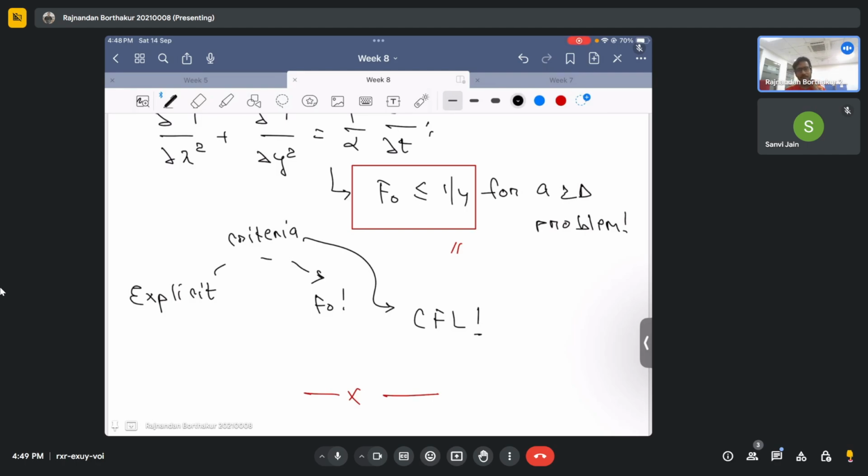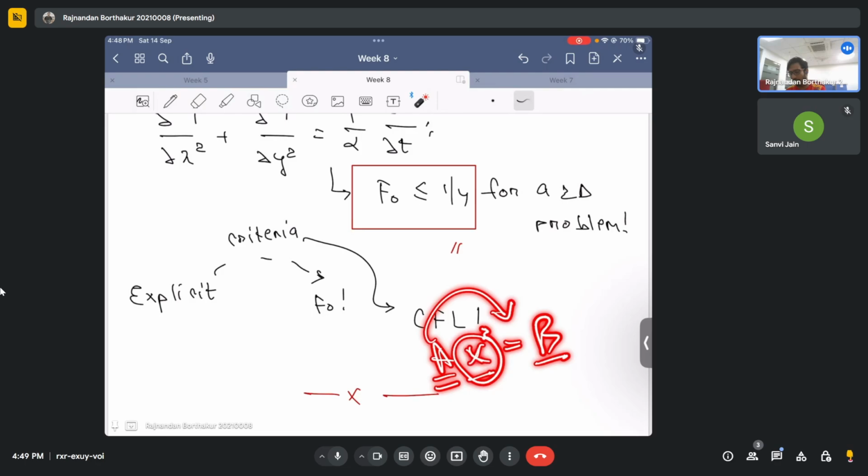Did you understand at least some bit of how these things go on when we try to solve it numerically? Yes, we have not done one thing. So far we have just learned to discretize the equation, but our job is not done there. After you discretize the equation, writing the algebraic equations, you need to form the set of algebraic equations into matrix form, some A matrix times X equal to some B matrix. Basically you need to solve for this X matrix. This X matrix will store the temperature values at each and every node point. And you just need to take the inverse of the matrix to get the temperature value at each and every grid point or node point.